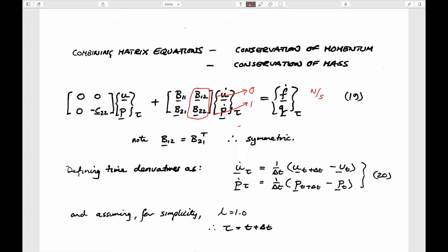Likewise, if you apply this fluid pressure to this, this is saying that you're not allowing deformation to occur, but you're allowing fluid pressures to change. And so the amount of fluid that would get squeezed out of this, because these would of course have no influence whatsoever, is because you have a rigid skeleton. It can't move because the displacements on the boundaries are not changing because of this term here, but the fluid pressure is changing. So in other words, if you drop the fluid pressure, then the fluid will expand, and if it expands, then it has to come outside of this control volume because now the fluid volume is larger than the pore space, and so it has to give you this flux.